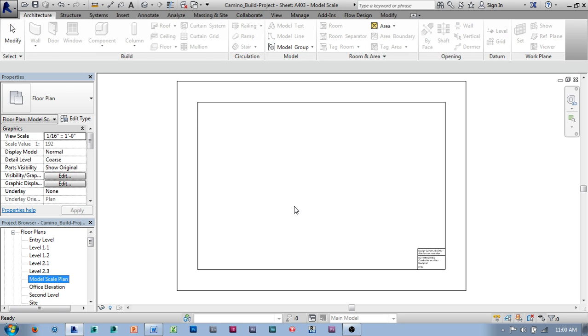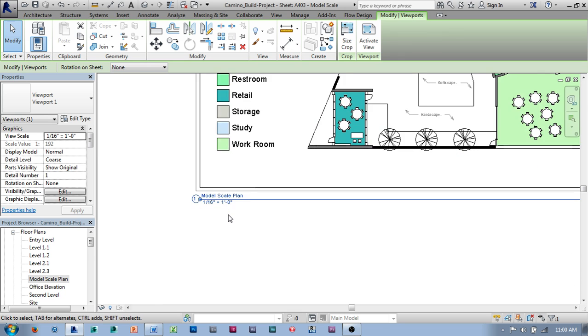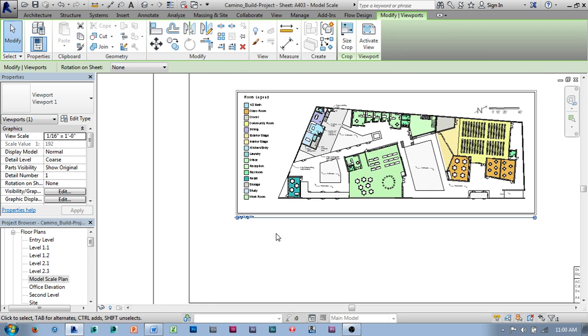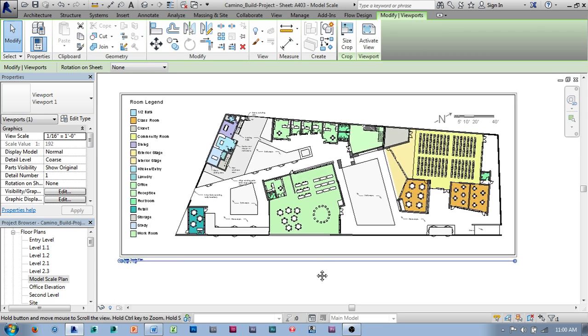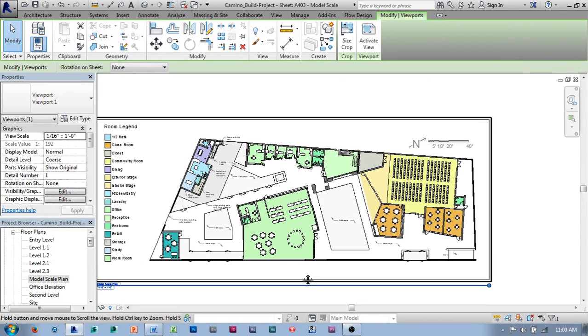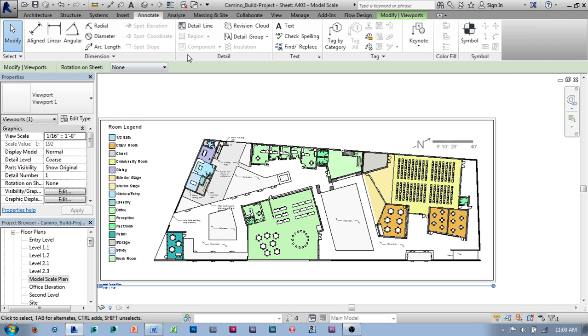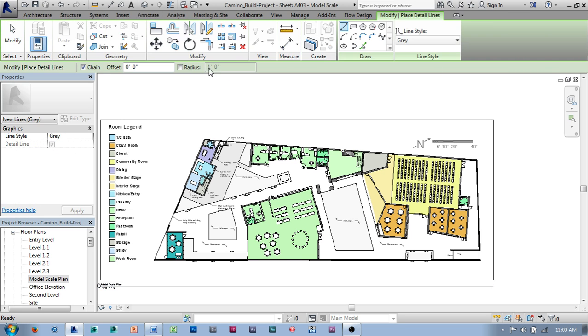And we'll drag and drop that right onto the page. So currently the scale on this is 1/16 of an inch, which seems like it's going to be a pretty good scale for the model. And now I know the Rep 2 has a build plate of just under 6 inches by 12 inches. So if I use my annotation tools, detail lines, I'm going to start drawing out a few lines here.